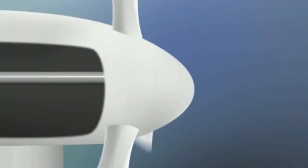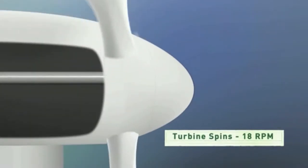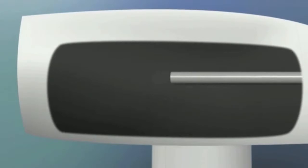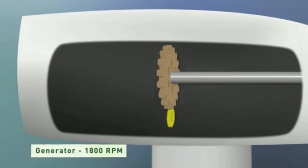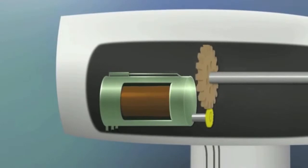Now the blades are attached to a shaft which only turns about 18 revolutions a minute, and that's not nearly fast enough to generate electricity by itself. So the rotor shaft spins a series of gears that increase the rotation up to about 1800 revolutions per minute. And at that speed, the generator can produce a lot of electricity.